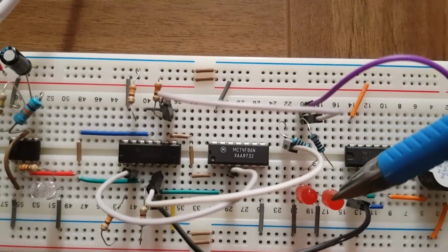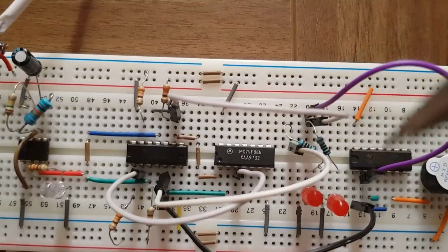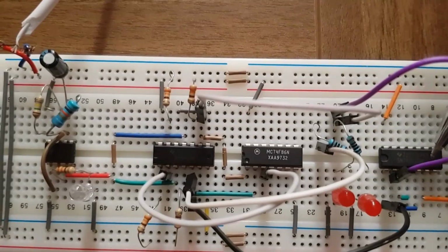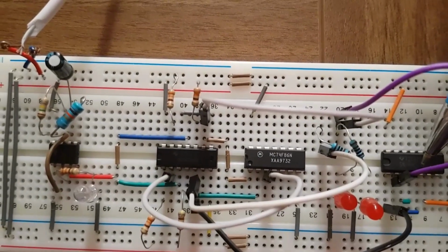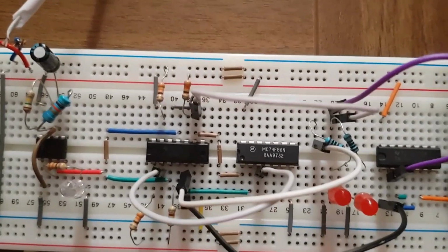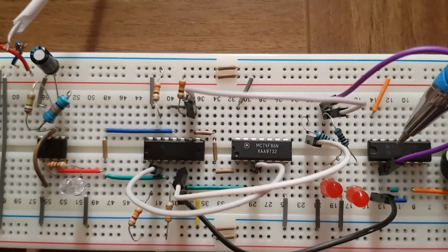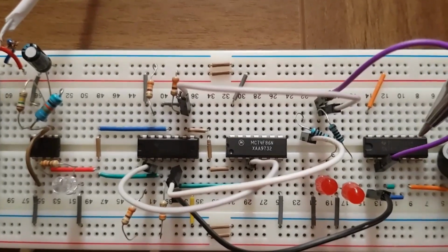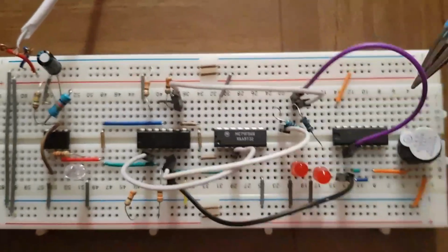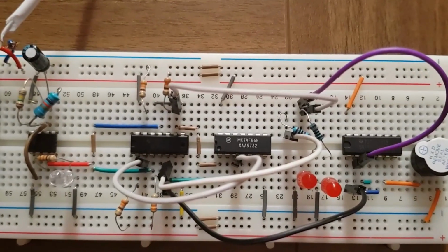When the 1 1 state is reached, I supply the outputs of the D flip-flops to the NAND gate. I didn't have an AND gate, so I constructed it from NAND gates, and that's a quad 2-input NAND gate, which means there are 4 NAND gates inside this element. When the 1 1 state is reached, the first NAND gate will give the output 0, and I supply this output to the input of the second NAND gate, which here simply plays the role of an inverter. So it will give an output of 1, and the buzzer will give us a signal at the 1 1 state.